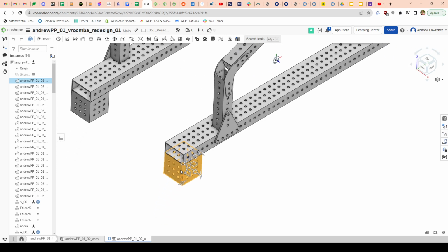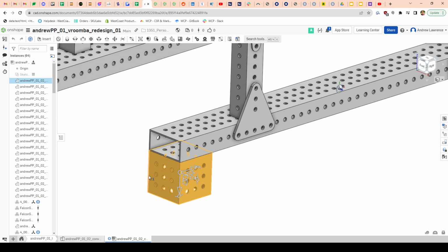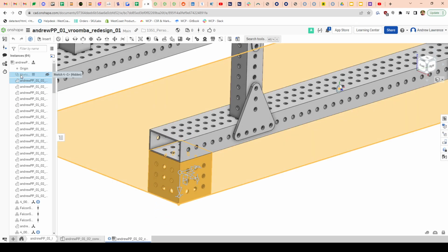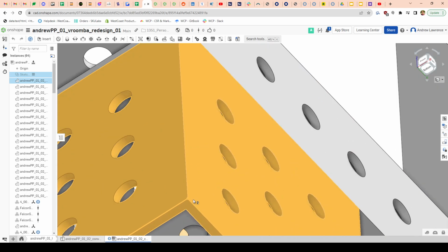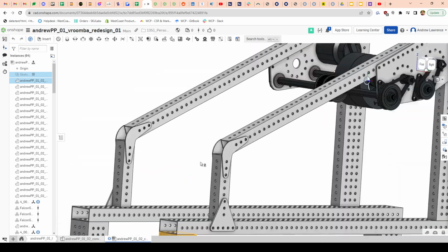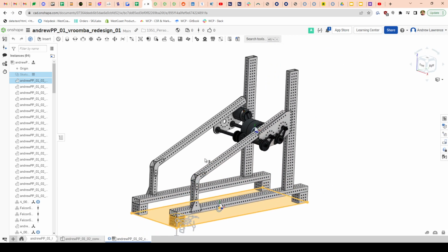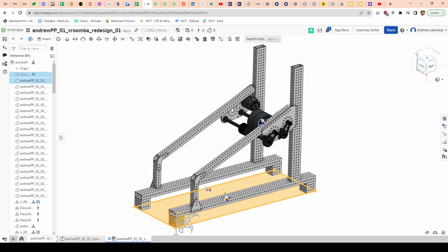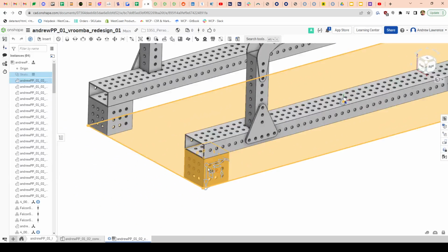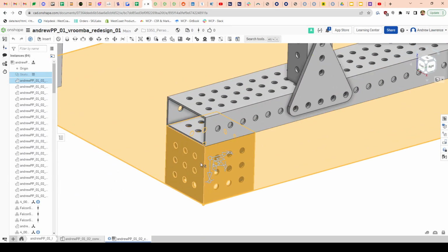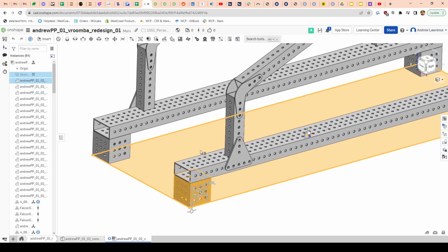From there, I inserted this tube, and I inserted it with a mate to the sketch. So I used a mate connector with this corner right here. So that may place that pretty rigidly where I wanted it. And again, this rectangle is actually driven in size by the correct placement of this tube. That's why I model it the way I did.